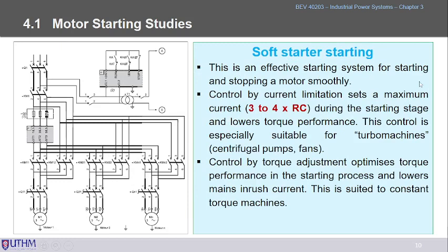And the soft starter, so if you are using the soft starter, that means you can ramp the starting current, ramping it from 0, slowly going up to the maximum current, or you can control it by the voltage. Slowly you ramp the voltage. That means we start from 0 and slowly we increase the voltage, ramping up to the maximum voltage. And with this kind of starting method, we estimate that the starting current will be 3 to 4 times.